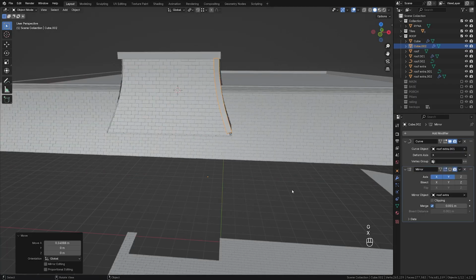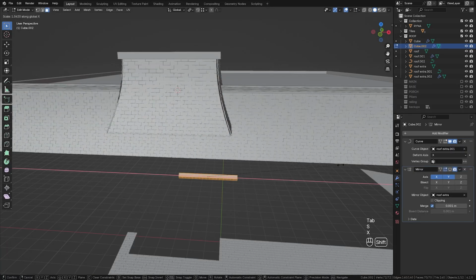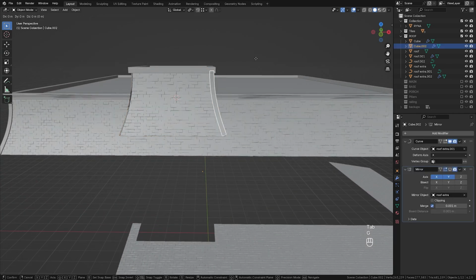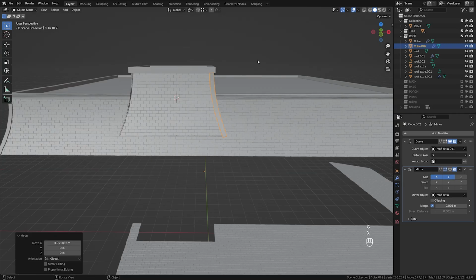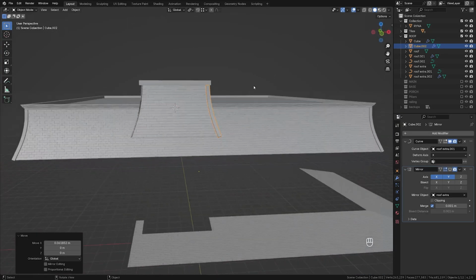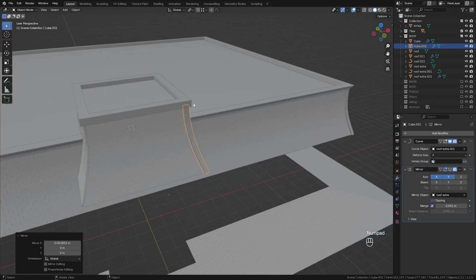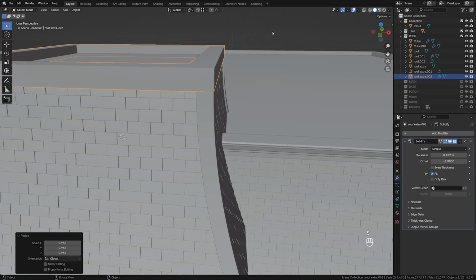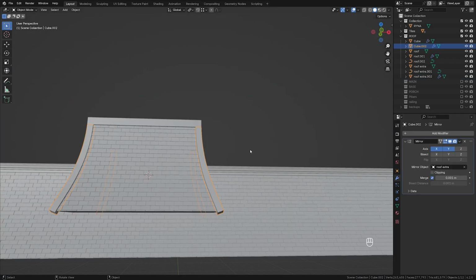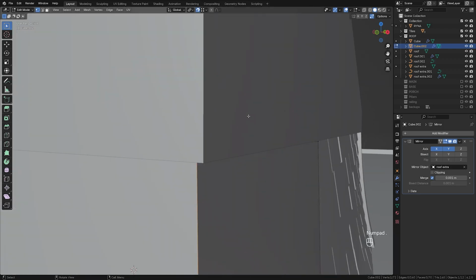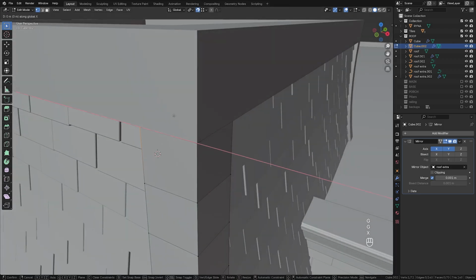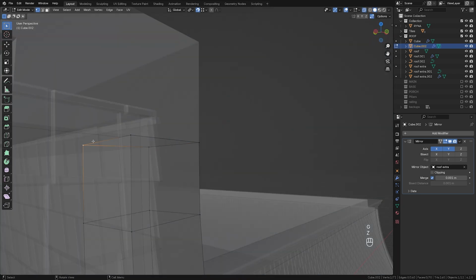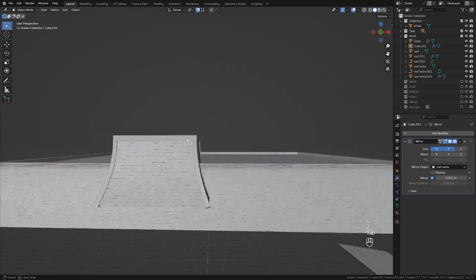Now I'm going to repeat the entire process that we did for our roof supports on our secondary roof supports. I'll speed this up and just briefly tell you what I'm going to do again. So first, we're going to adjust the size of the vertical supports, make them smaller. Then we're going to make the top support smaller, scale it down, apply the curve modifier, use the snapping tool again to snap one of the vertices to the bottom corner of the top support, and then use the snapping tool again to align the other vertices with it on different axes, specifically the z-axis.